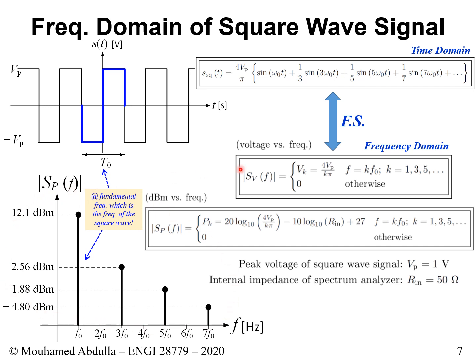So you see how the Fourier series is incredibly powerful. We had no idea how to determine the frequency representation of it, and now we can. It's all thanks to Joseph Fourier, the guy who came up with the Fourier series approach. Okay, and why do we do this? Well, this enables us to have an extra dimension in analyzing the signal. It enables us to figure out the bandwidth of the signal. The time domain does not give you a clue on the bandwidth of the signal. This gives you a better understanding of the bandwidth of the signal.